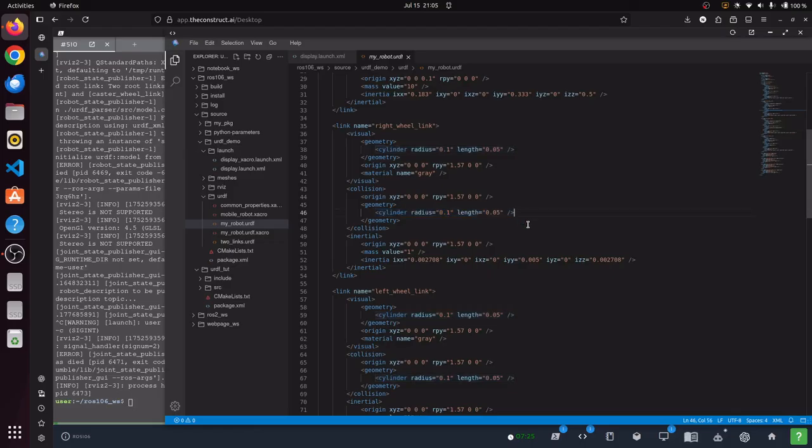One common thing is, people don't usually build URDFs by hand. They usually look for pre-built URDFs available on GitHub or other platforms, and then modify them according to their needs. And in some software like SolidWorks, you can convert your CAD files to URDF directly, so you don't have to write all of this by hand. But you should know how to write it, because if there are any issues, you need to know how to debug them.